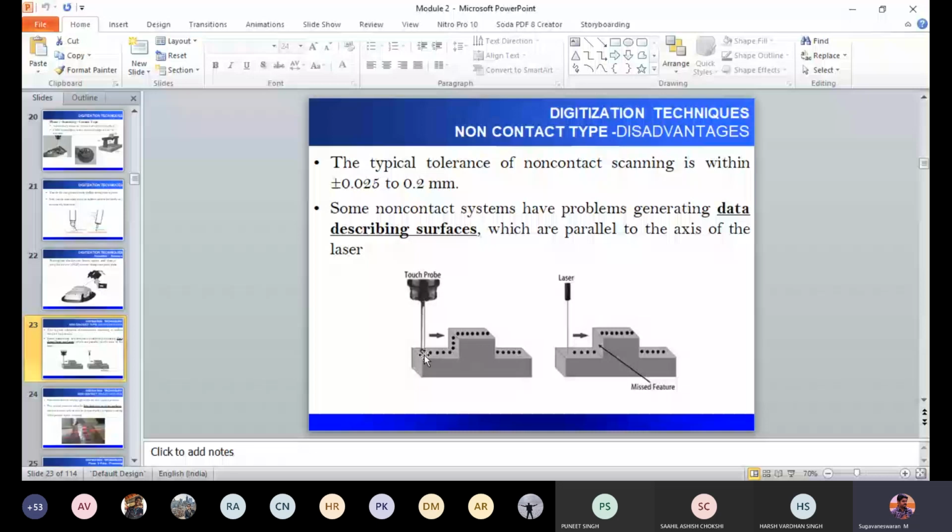So to understand the dimension, I'll take a probe and I'll take some point as 0, 0, some point which is out of a part. I will record that point. I'll touch the point and make sure that that point is 0, 0, so that I will record it as 0, 0, my origin position. From origin position, I can gradually move the tool tip and I'll touch at certain place.